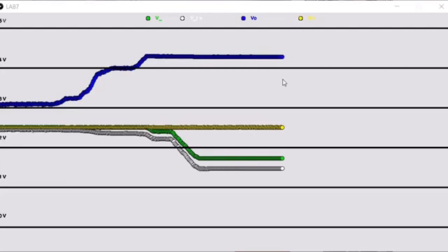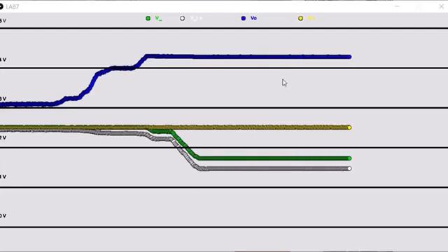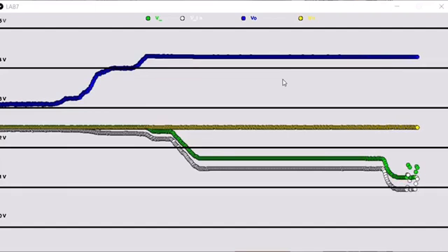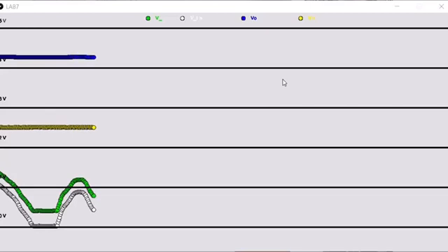And now when Vout is at saturation, there is a bigger difference between the Vin and the V minus, since the voltage across R1 is greater, while our Vout remains constant.